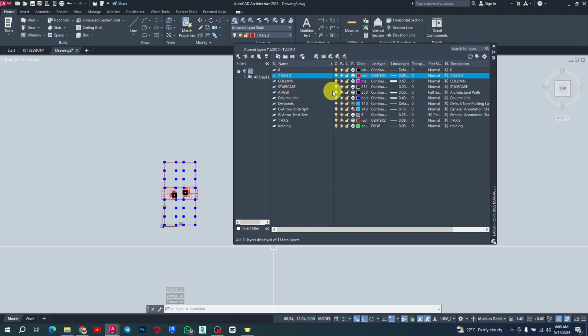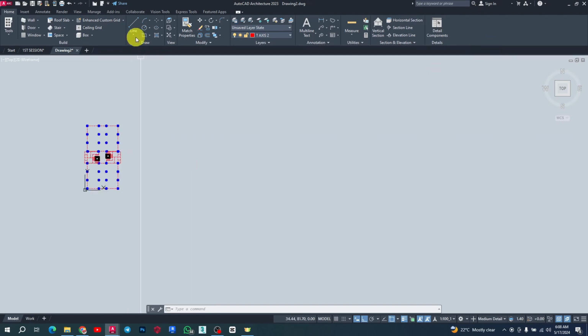Something very important that you want to go with is your dimension. You probably want to choose a particular layer type and color for your dimension. This comes into effect when you choose everything under your dimension style to be by layer, so you see the particular color appearing. So I'm going to go here and close this one, then start my drawing.